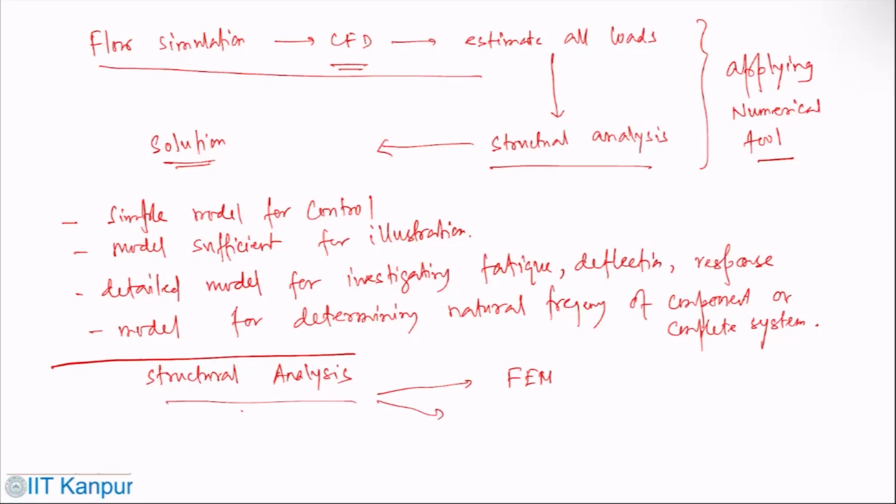Or one can use the lumped parameter method. A lumped parameter model is one in which a non-uniform body is considered to be made of a relatively small number of bodies, which can be simply characterized. This characterization may consist of as little as the mass of the body, or it may include other parameters as well, such as stiffness.